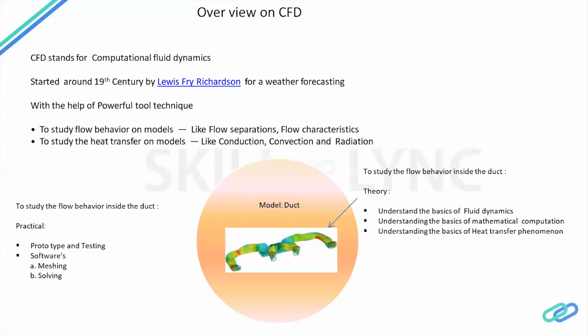Apart from this basic continuity equation, we need to go with the dynamics part of the fluid, that is called the Navier-Stokes equation. The Navier-Stokes equation is similar to what you read in engineering, called Bernoulli's equation. The only difference between Bernoulli's equation and the Navier-Stokes equation is that the viscosity of the fluid is taken care of by the Navier-Stokes equation. In the case of Bernoulli's equation, the viscosity is not considered, so the fluid is assumed to be inviscid.